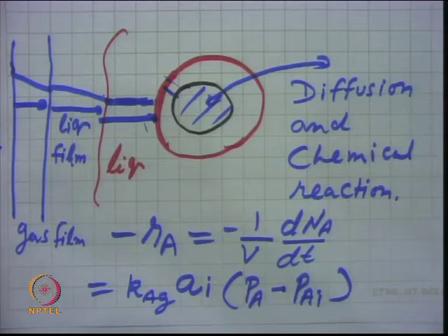If your liquid side or gas side resistance is dominating, then obviously one would like a bubble column reactor or a slurry bubble column reactor, with a large volume of liquid or large interfacial area. So, a good sparger design where you have small gas bubbles diffused through the liquid, depending upon the solubility of the gas. All these designs will be important: a good sparger, a good agitating system, your catalyst particle size. Everything is important because you need to minimize all these resistances.